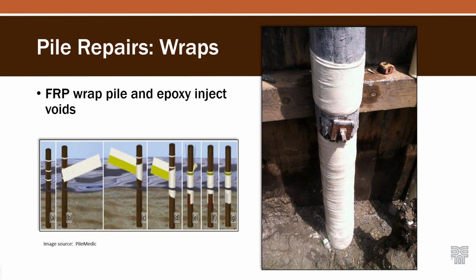One thing I would say is as you do these repairs, the ability to inspect the timber on the inside becomes lessened. I've seen cases where you want to include reinforcing steel and a bigger concrete or grouted annulus between the timber and the fiberglass jacket so that you get more of a structural repair out of it. But they're definitely an option that's out there.